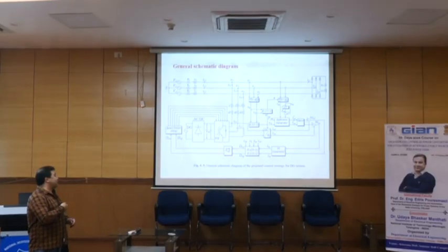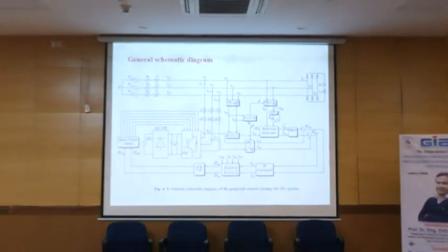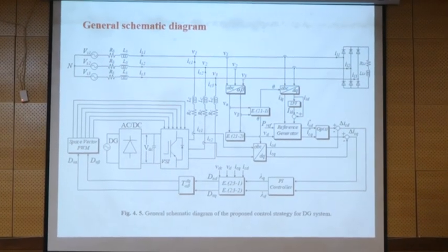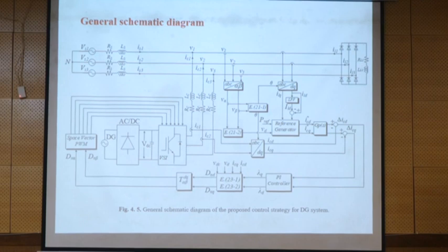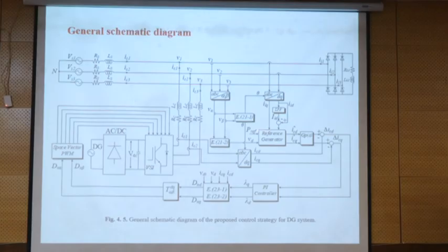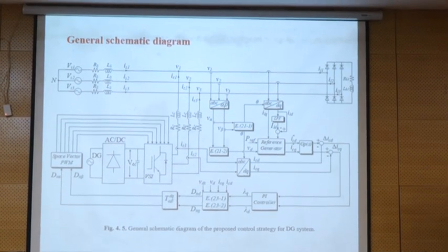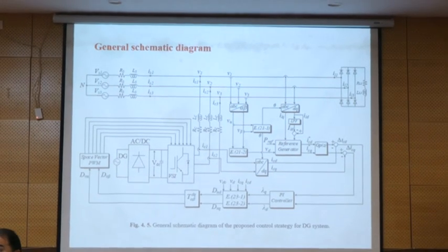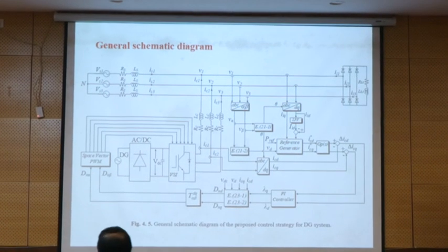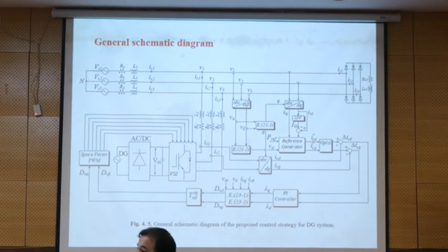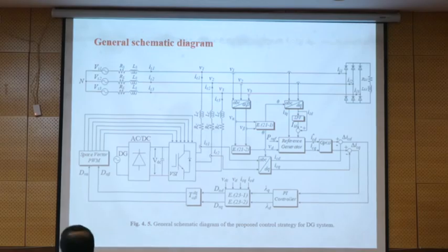So based on that, they provide the switching and 6 signals go out, which are complementary. So if this is 1, this is 0, this is 0, this is 1, something like this. Each leg has 2 transistors and they are complementary. So by this assumption, we provide the power to the grid. And these references can be chosen based on what you are going to do. It can simply be said that reactive power is equal to 0 and active power follows like this. It depends on what you are looking for. But here we mentioned this in the discussion.